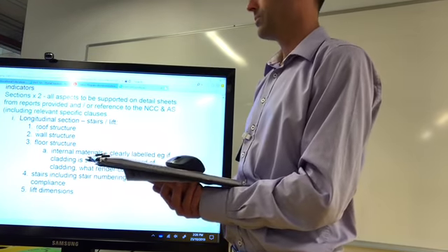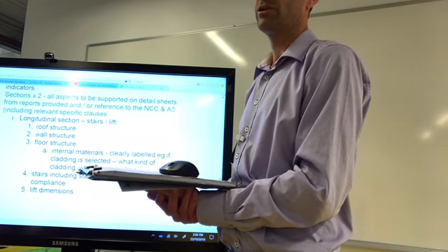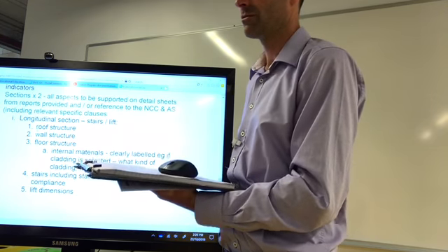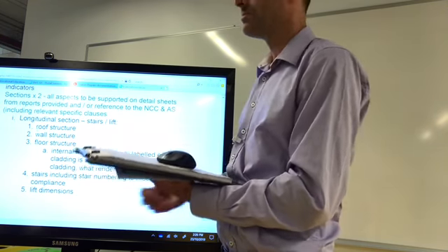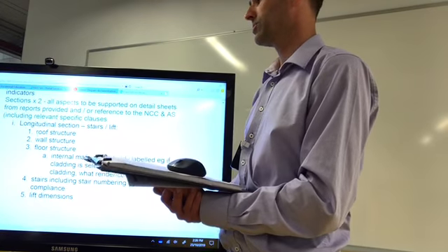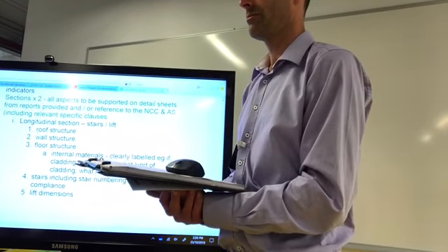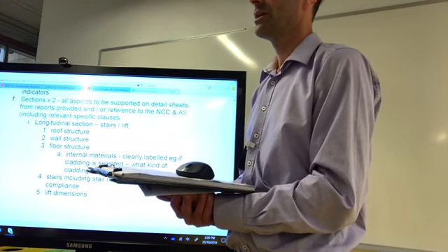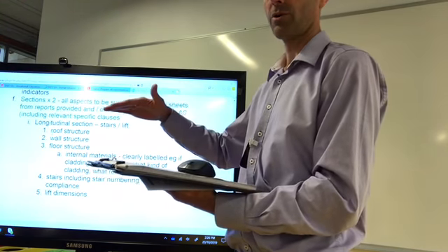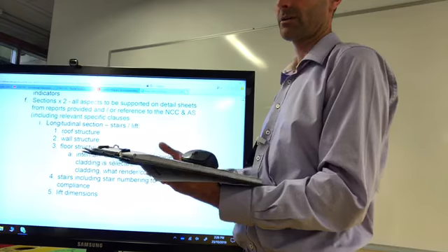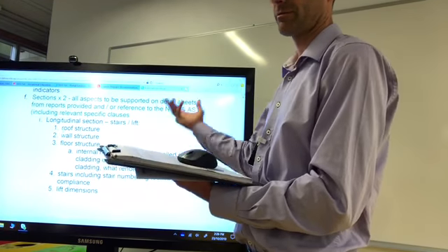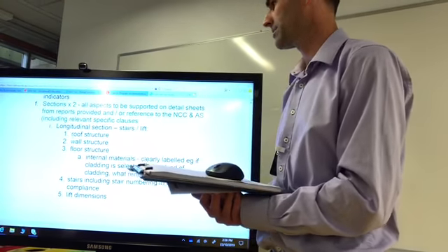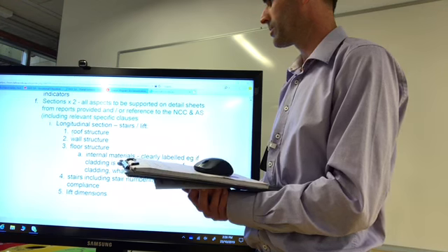So there are two options really you could go with for your roof structure for this building. One of them is that you could go with it being a metal decking roof with a pitch to it, and then that slopes toward a box gutter, and that box gutter then is linked up with rain head and your downpipes. So that's one option you can go with.